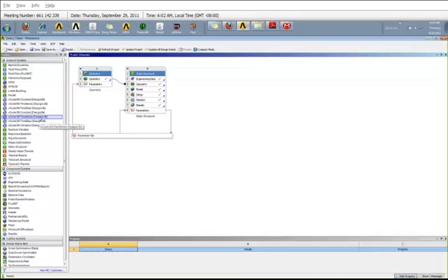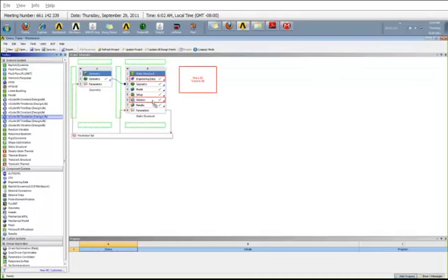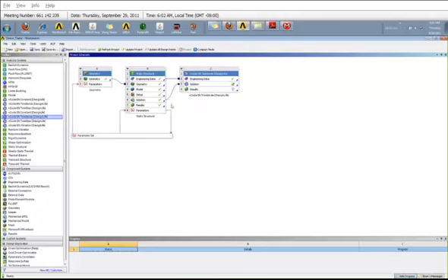So in this demo, I'm going to do a stress life analysis using the time series. I'm just going to drag and drop it onto my static structural, onto the solution of my static structural. So my solution gets transferred to the nCode DesignLife, and the engineering data will also get automatically transferred. Now let's go ahead and open up the DesignLife.